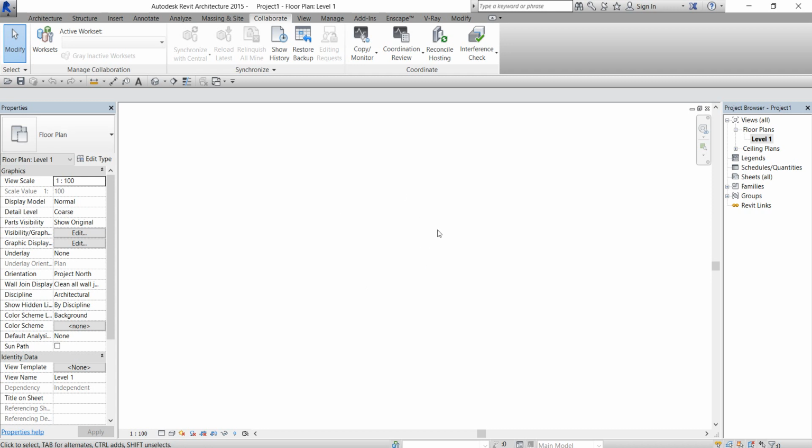But something here is that we are designing based on new assignments, but before then we have to set some certain categories of elements. So the first thing we need to do is to bring our elevation markers around here, because there is no way we can be working without having elevation. That's the point of architecture.